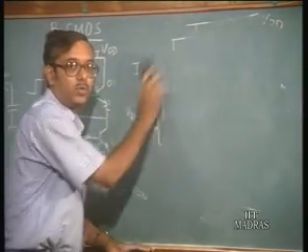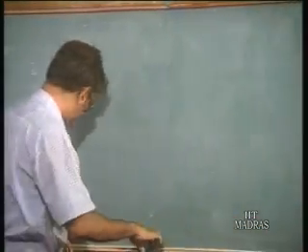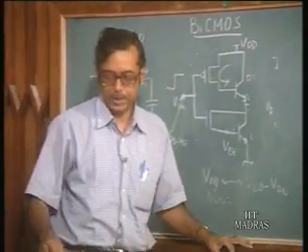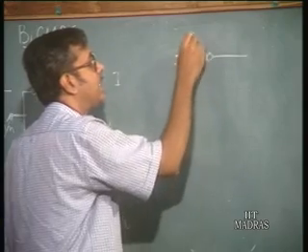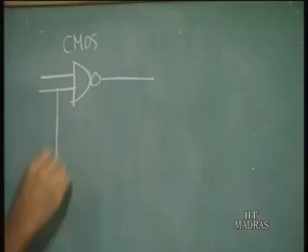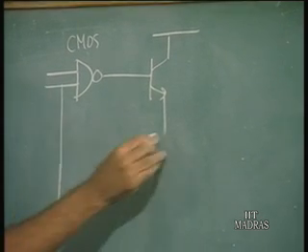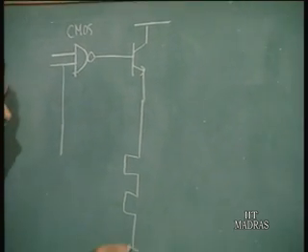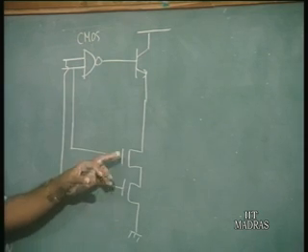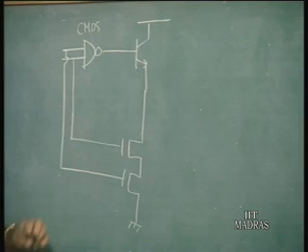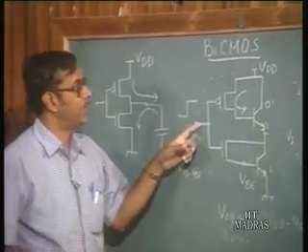So, what is done is we have low voltage BiCMOS circuits, where an attempt is made for full swing operation. I will just give one example, which has been used in the Pentium chip. Okay. So, what they do is we take a NAND gate. So, you have this is basically a CMOS NAND, which goes to the bipolar transistor here, and then here the pull down is actually done with the help of NMOS. Okay. So, we do not use a bipolar transistor in the pull down because of the fact that at low voltages it is no longer advantageous to do a pull down because of the extra VBE drop.